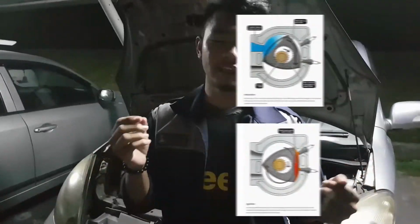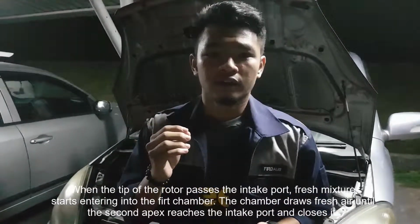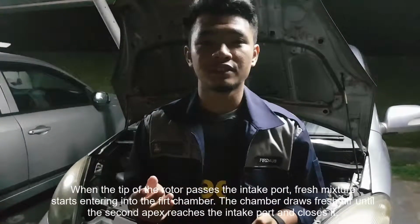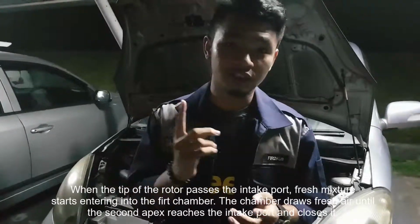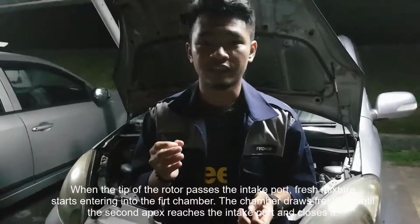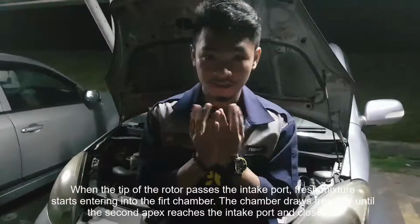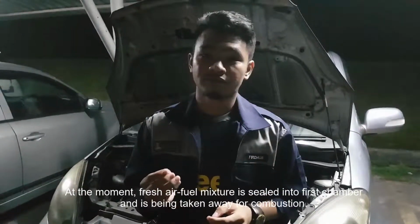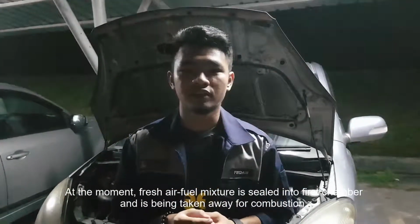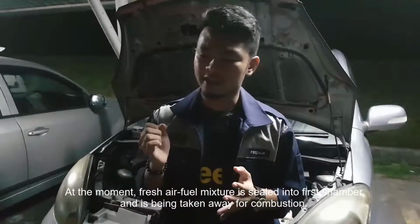First of all, in intake, when the tip of the rotor passes the intake port, fresh mixture starts entering into the first chamber. The chamber draws fresh air until the second apex passes the intake port and closes it. At the moment, the fresh air fuel mixture is sealed in the first chamber and is being taken away for combustion.